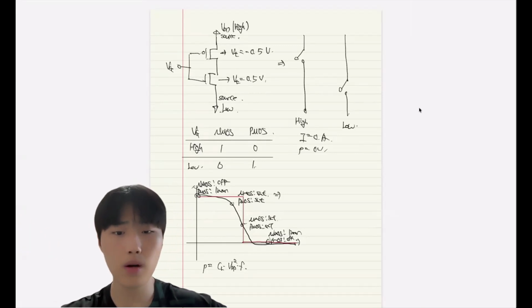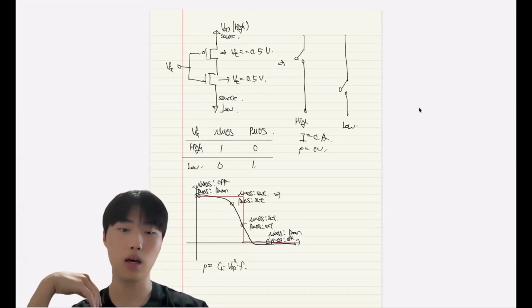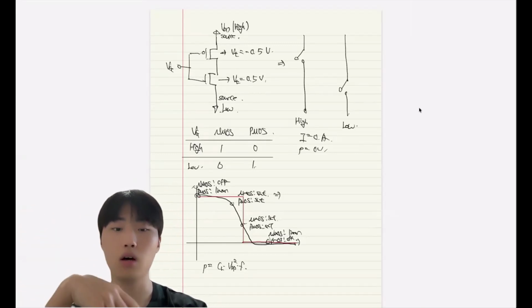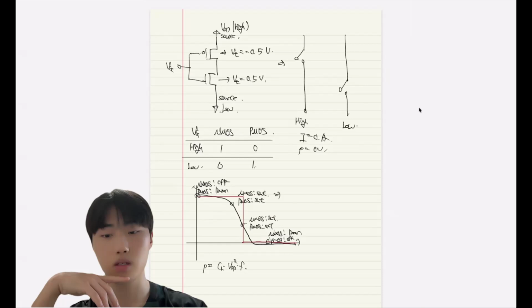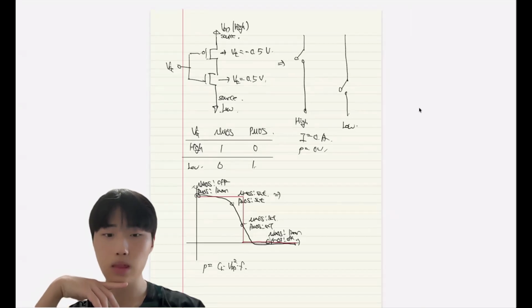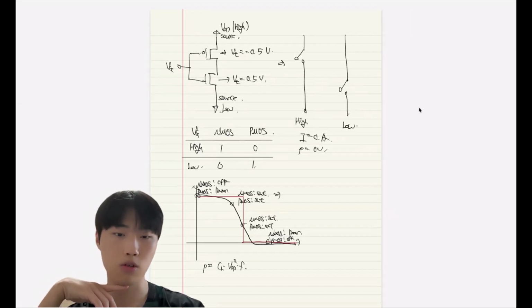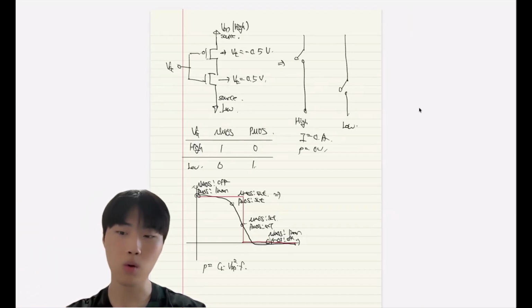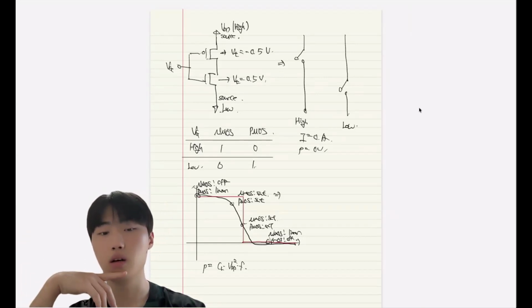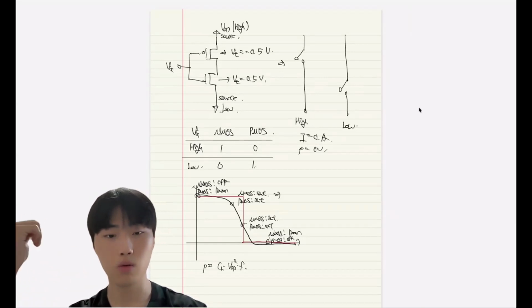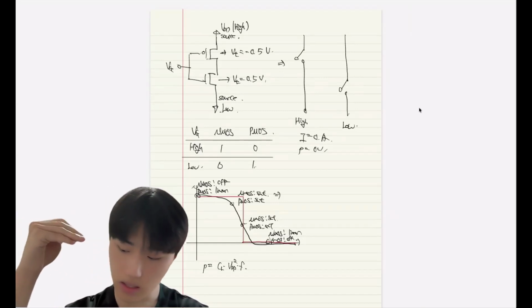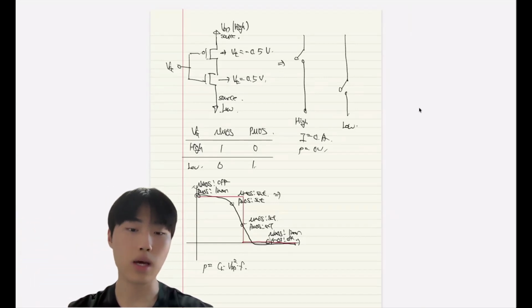And the V_DD squared is related to the subthreshold swing, as we had learned. So we have to find a solution about the subthreshold swing, and we can lower the V_DD, the turn on voltage. And the problem is the C_L, the load capacitance.